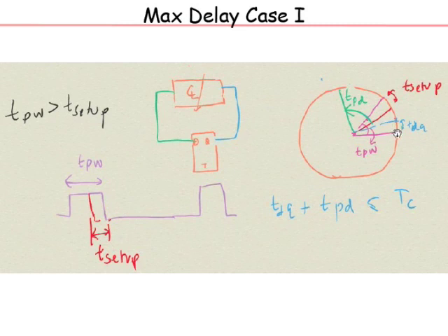Let us say I set it up where the logic delay is very small. As soon as the positive clock edge happens, the latch becomes transparent. The data flows through the latch, there is a TD to Q, then it flows through the logic, which is TPD, and then it waits. The next time the clock edge comes, again it flows through, goes, waits.